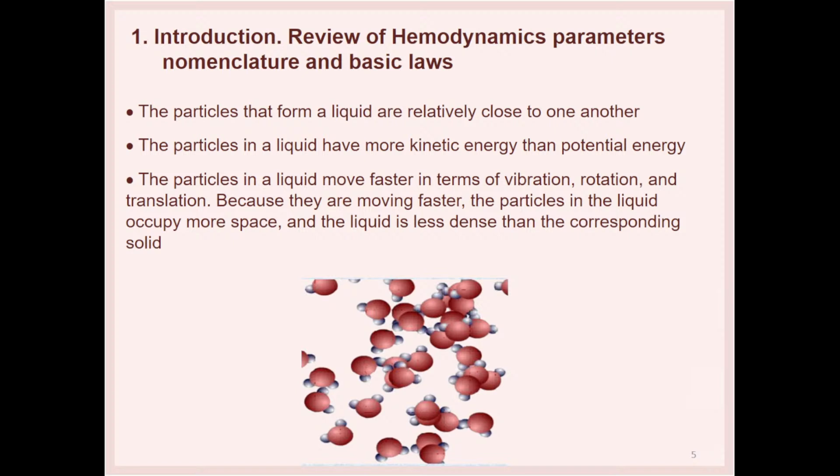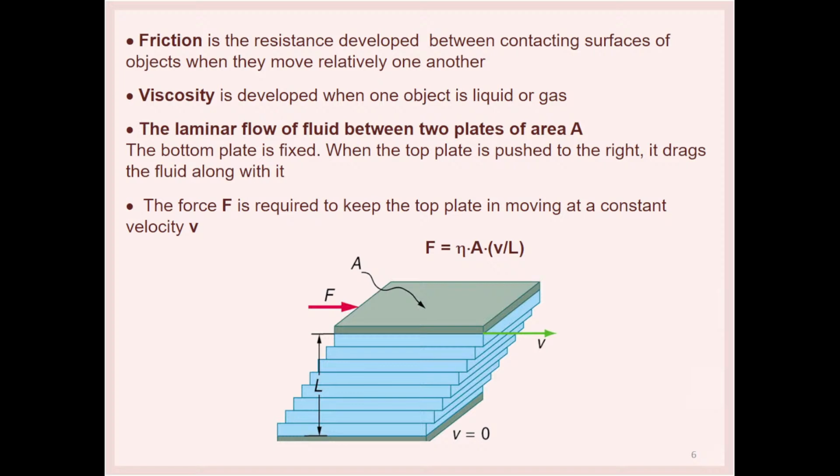The force is required to arrange motion of any object. The simple experiment demonstrates how liquid can be forced and moved. This figure shows two flat plates separated by a thin fluid layer. If a lower plate is held fixed, a force is required to move the upper plate at a constant speed. This force is needed to overcome the viscous forces due to the liquid and is greater for a highly viscous fluid than for a less viscous fluid.